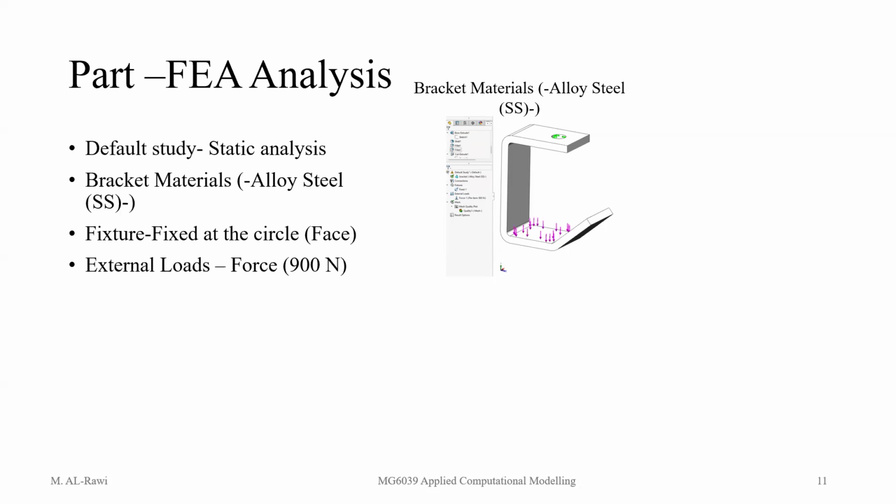When you see the bar underneath, double click on that static one and name it default study. You can call it from here as well, and tick OK. You can name it earlier, or in case I forgot, you can amend it from there. Now, what is generated for you?